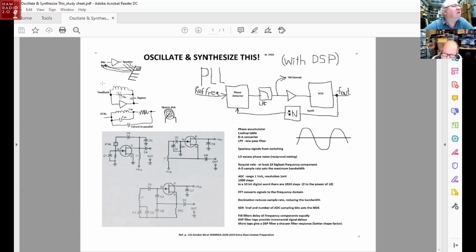The next little circuit down is one that we introduced last week in the receivers, where we made a local oscillator out of an oscillator. You have an amplifier, which is again the triangle. This is an LC oscillator, and the bypass capacitor is sitting here so you don't make a DC short through the choke from the output of the amplifier back to the input. If you did that, the amplifier is probably not going to work, may damage or destroy the amplifier. And so you have to have a bypass capacitor.